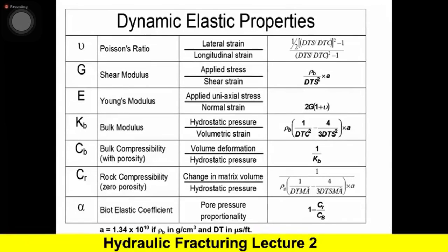A lot of parameters, so we're not going to get into that. But which one would you use? Most people are going to say dynamic, and the answer is no. It is use static values in designing the fracture.